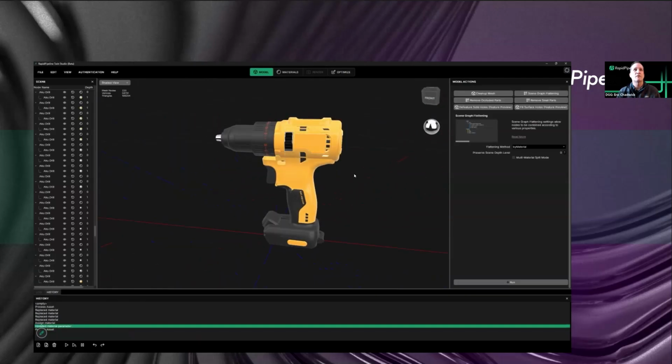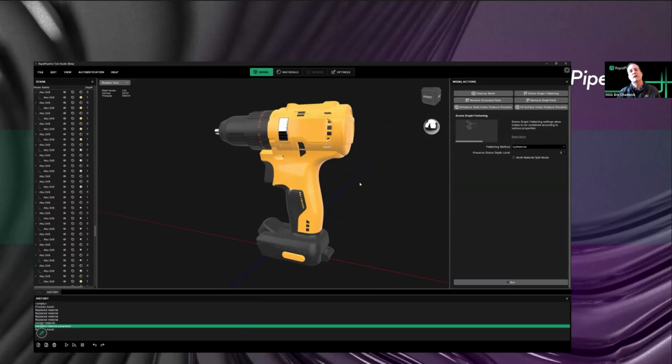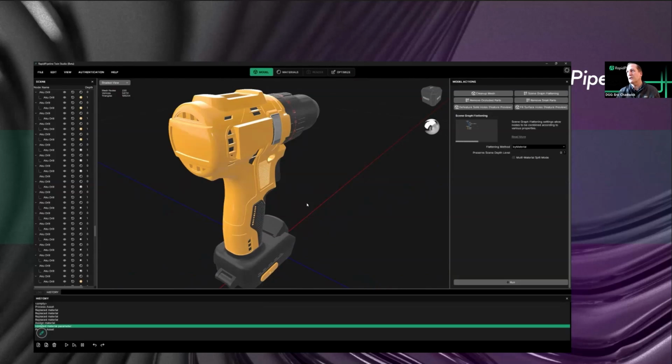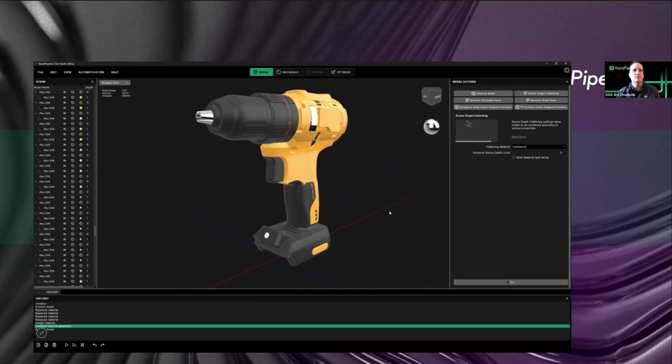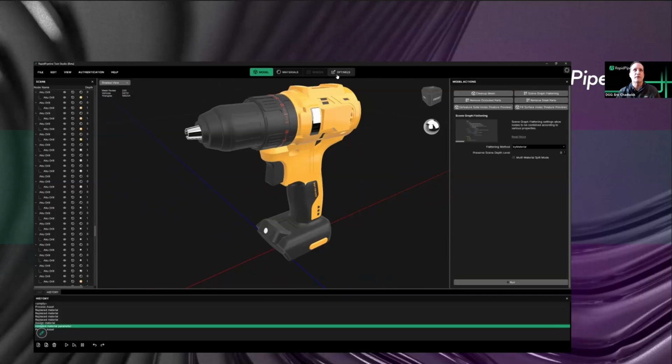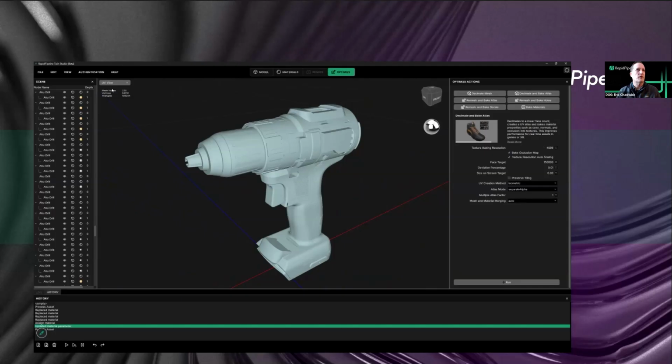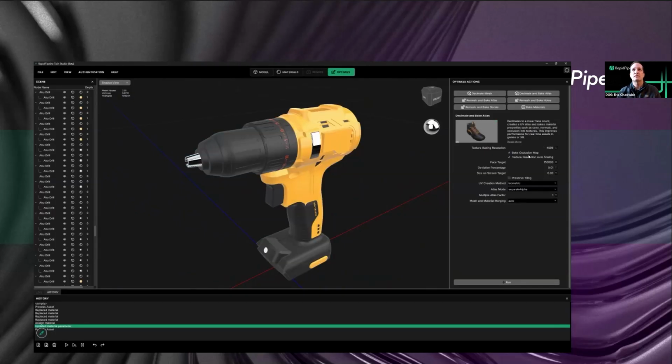And let's try a different way, which is often for PBR rendering, you want additional textures to be generated. So ambient occlusion is a great example. I want to generate ambient occlusion for this thing and have it be a beautiful model. That's part of our optimization pipeline. So we have a whole texture baker that can go through and bake an occlusion map for a model. This thing, I think, doesn't have any UVs by default. So what this does is we'll automatically create a texture atlas for the model at the resolution you specify, bake an occlusion map, and apply it to all the materials.